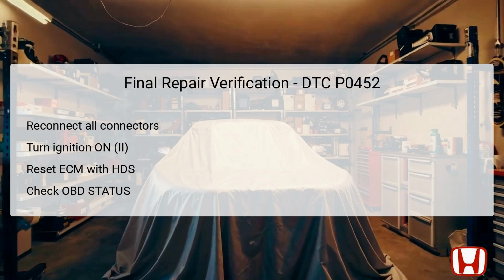It's also crucial to perform the ECM idle learn procedure, ensuring that the engine management system adapts to any changes made during repairs. Finally, monitor the OBD status for DTC P0452 using the HDS to determine if the status reflects passed, indicating successful resolution, or any other status which would prompt further investigation.